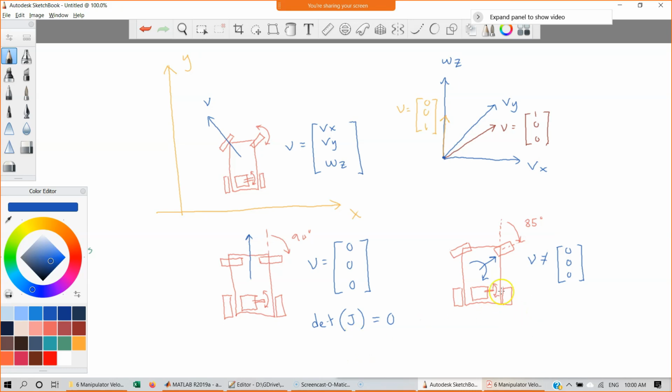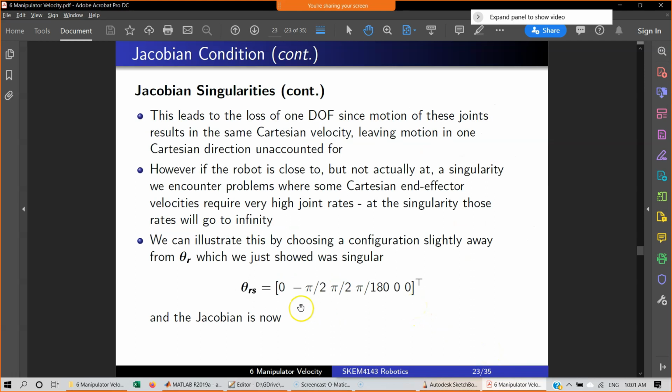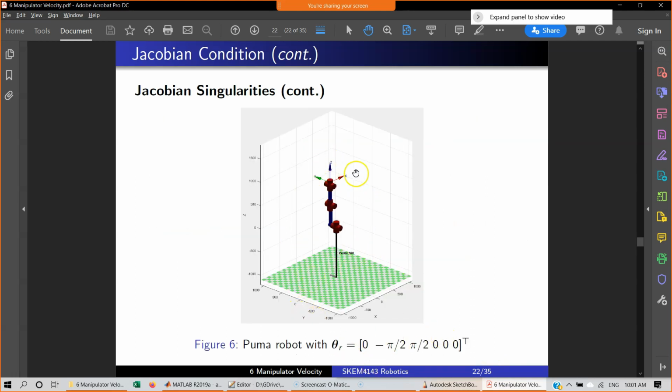But of course, the catch is your motor has to work really, really hard to produce some motion. So this is not in gimbal lock situation. This is not in singularity. This is in singularity. So similar problems we can have in robot arm. In this configuration, we can have the gimbal lock problem where we will lose some degrees of freedom, which means there are some spatial velocity values that the robot cannot achieve from that configuration.